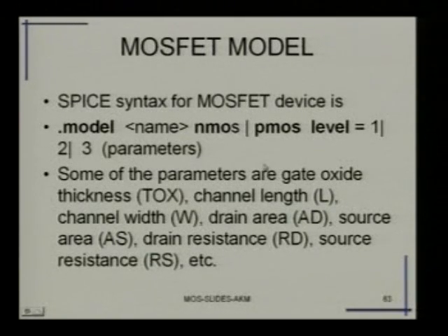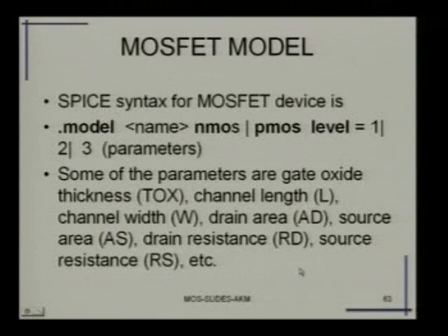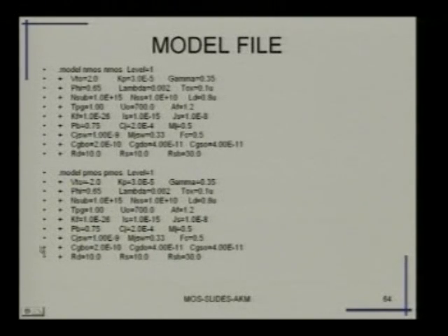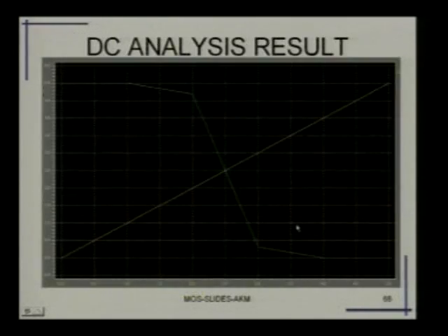There are now today the model 49, I think much later models, where you merely specify some of the parameters like thickness of the gate oxide, channel length and source resistance, and then use a computer to analyze. And a typical model file, you do not have to look at this. These are basically the way you specify the model parameters and analyze. The typical analysis of the SPICE input will be something like that.